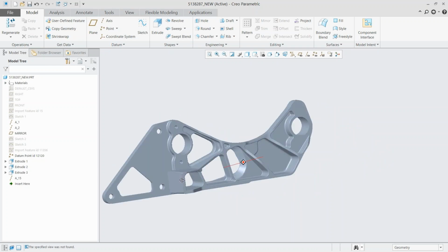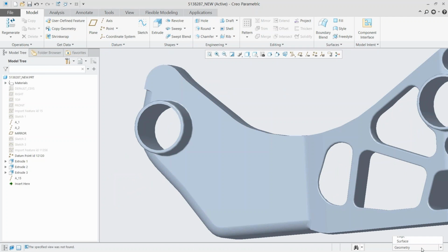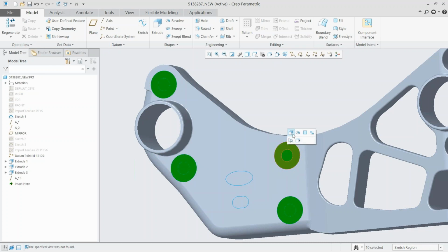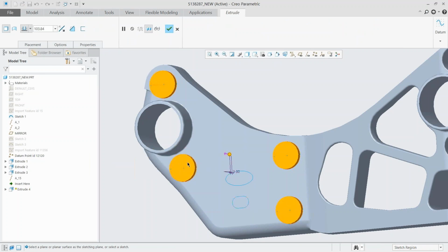To start with, we're going to be looking at some of the new sketch region capabilities. So we're going to go ahead and turn on our sketch regions here, view those. And we're just going to start selecting some areas. You can see that we can select any enclosed area that we want to work with. So you don't have to work with the whole sketch necessarily. You can pick whatever region you want, do whatever normal work you would do. In our case, we're going to do a quick extrude here.